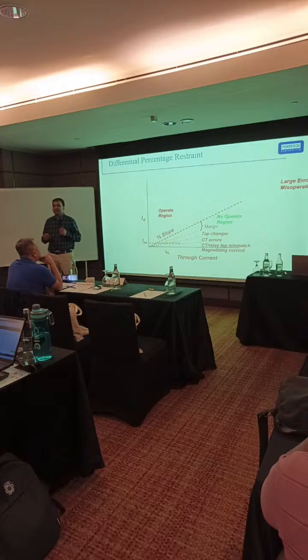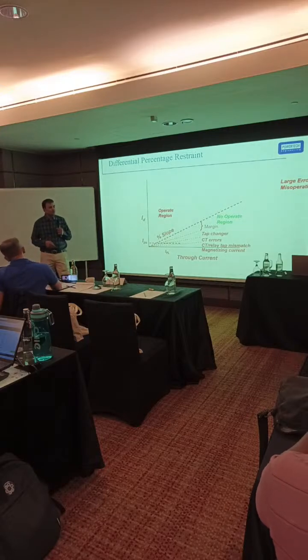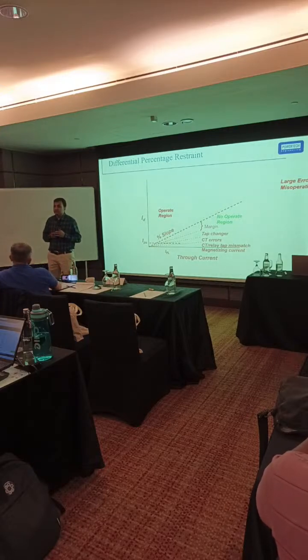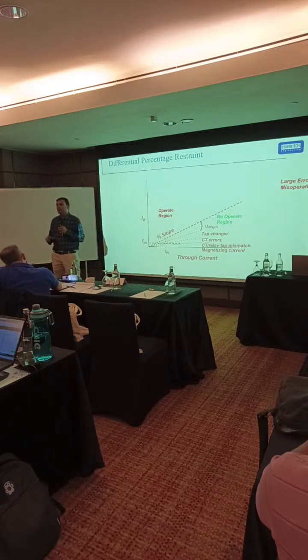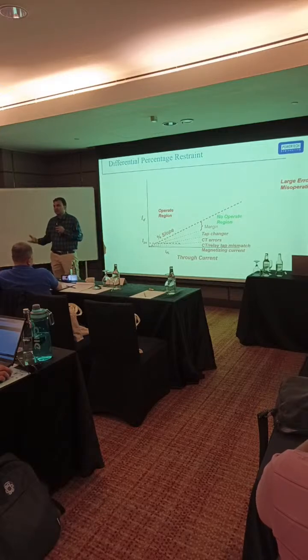No, not like that. If you are energizing and the relay is tripping, that means there is some problem in your setting. You should first analyze the fault DR. If the differential is tripping on the first charging, then there is a problem in your setting, so you should analyze that from the fault DR. You can easily analyze how much current and what factor caused the differential relay to operate.